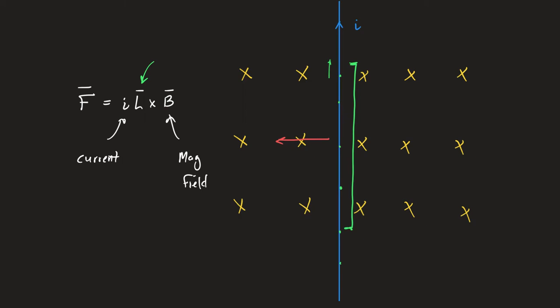Now, there are a couple of caveats here, but let's hit the high points. First, this is a generalized force that exists all over the surface of the wire. It's not applied in one place. So the entire length of the wire that is subjected to this magnetic field is experiencing a generalized force that's given by this calculation. But it's not concentrated in one place on the wire. It's distributed throughout the entire wire that's subjected to the magnetic field. There's some usefulness there. It means that if you're going to use the magnetic force, you get the convenience of understanding that your object isn't going to necessarily collapse under the application of this force, since that force is spread out through the whole thing.